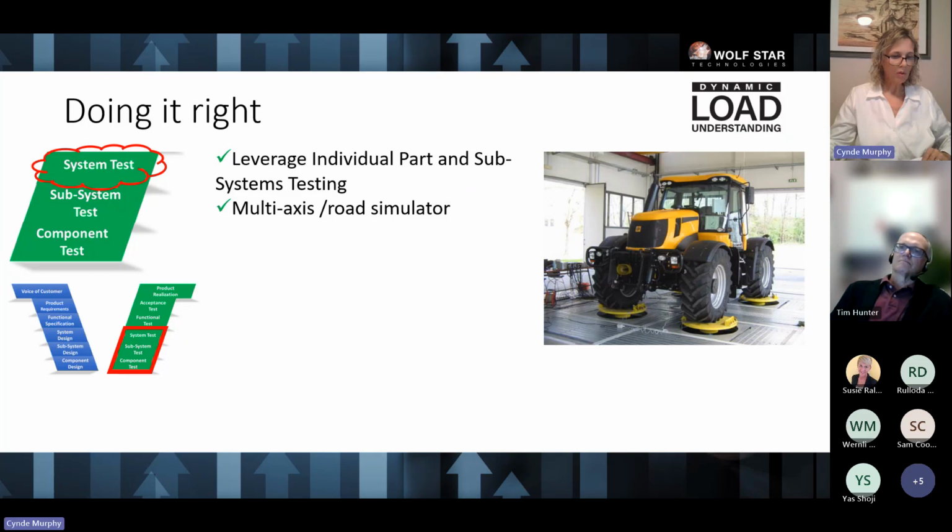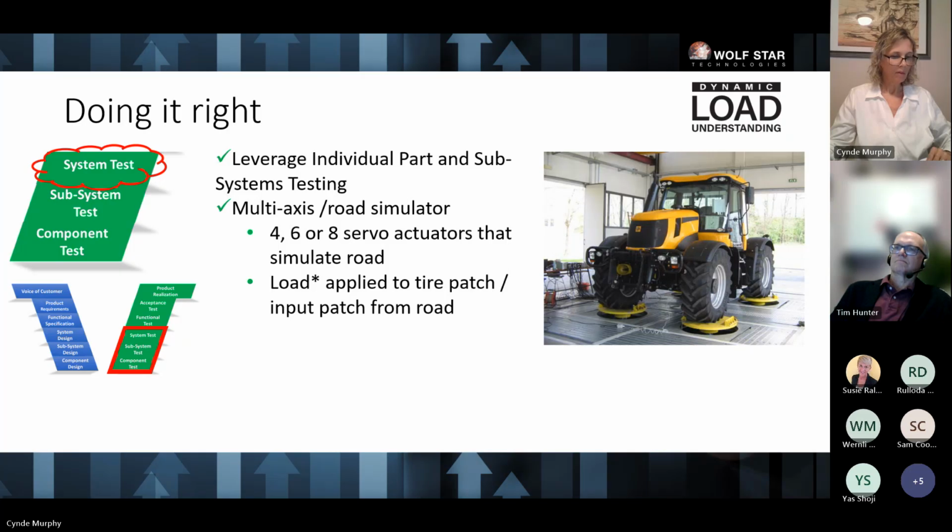This is usually a road simulator. The full vehicle is replicated in this test using a multi-axis servo actuator setup. This would use 2, 4, 6, or 8 posts. Loading for testing is applied to the tire patch where the system meets the road.